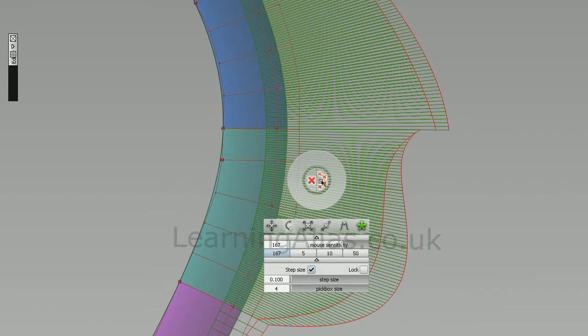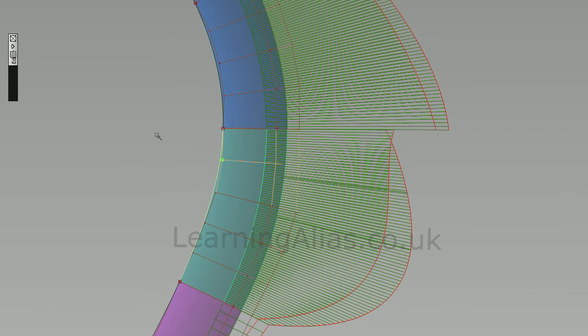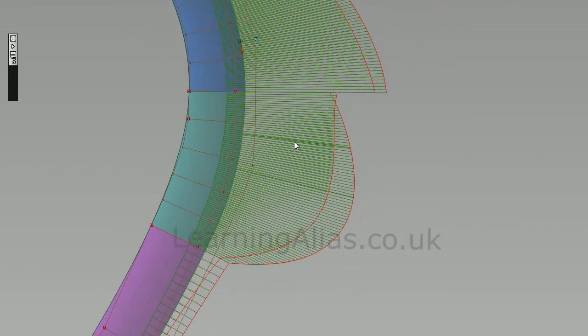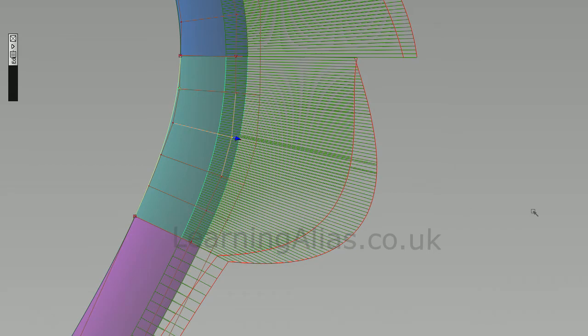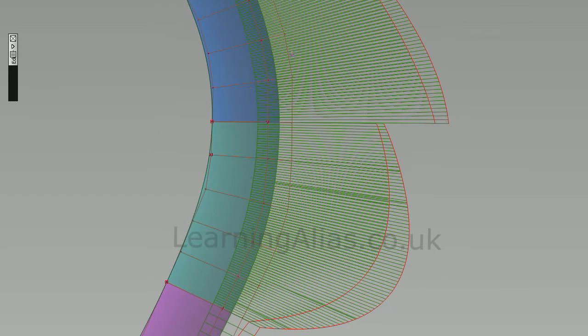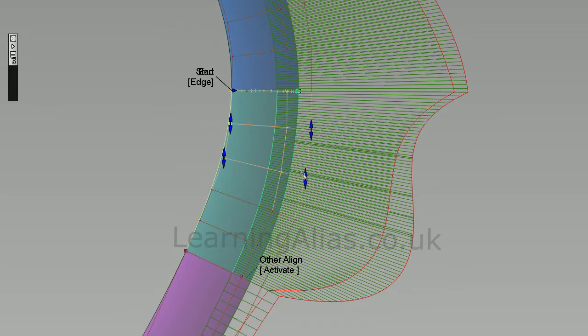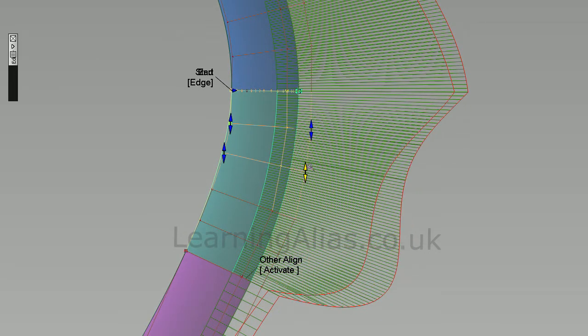So now what we can do is turn the controls for these surfaces on and delete their history. Then you can see rotating the hulls or pulling CVs in XYZ direction or NUV direction, what kind of effect it has on the combs. So the comb is showing us that we've lost G2 continuity, so we'll realign the lower surface with the upper surface.